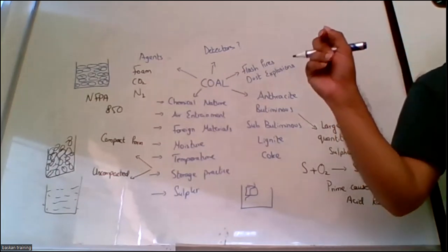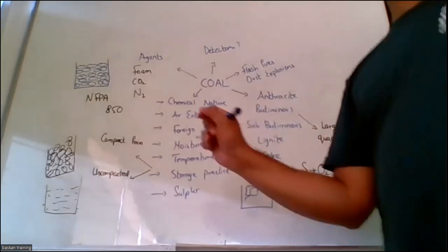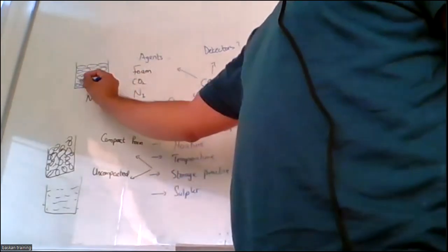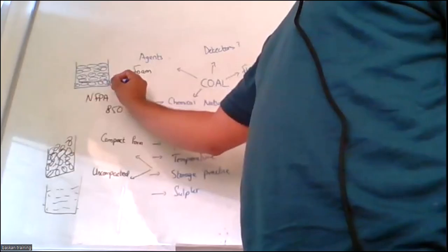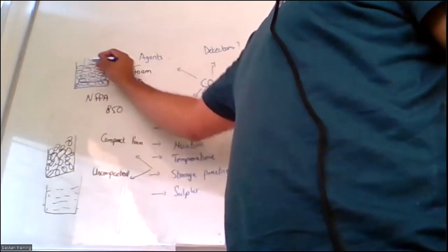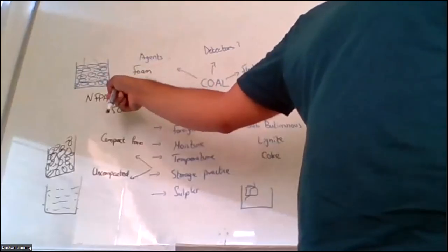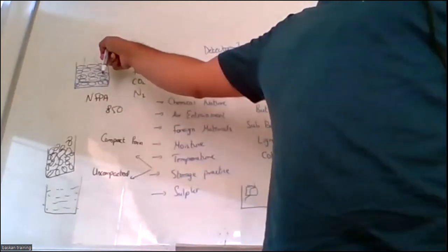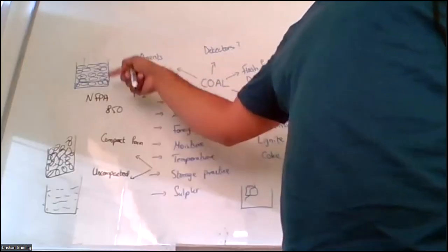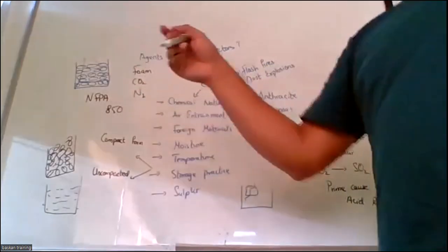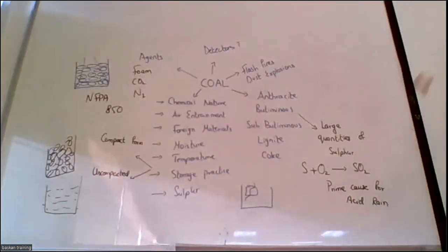The temperature at the bottom of the coal is much more important, because the heat is going to start from there. If the temperature is 57 on the surface, it means the bottom has already reached 100. So if you want to detect heat at the very initial stage in coal, which type of detection mechanism will you use? What type of detectors will you use?